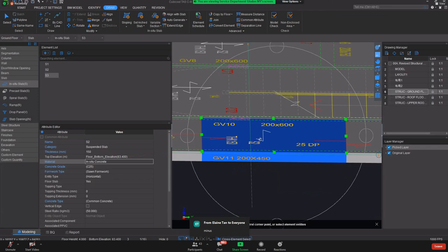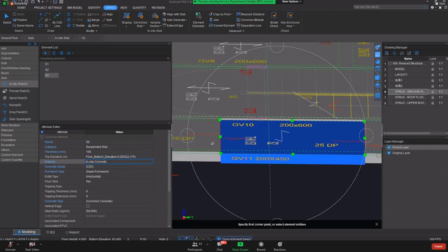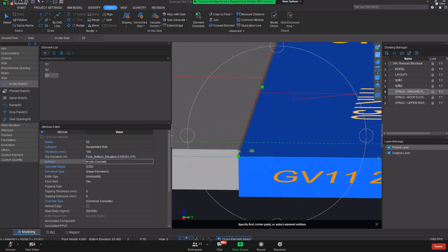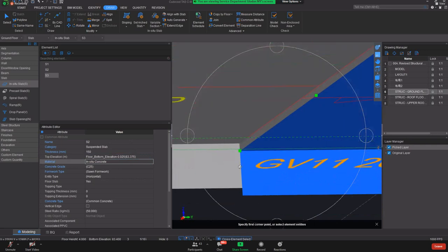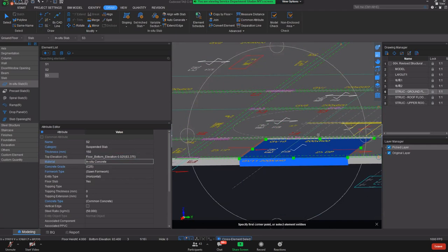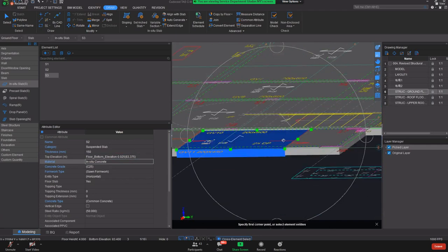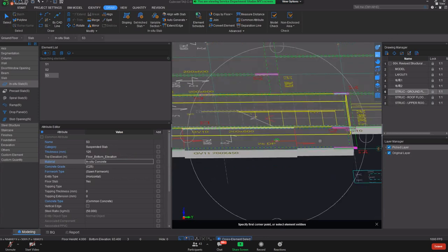Okay, so remember, you need to select this panel and double click on it, minus 0.025, and we press enter. Okay, then you can zoom in and see there is a drop, 25 mm generated. Similarly, I press escape. Okay, I press escape. I select this, the last panel.